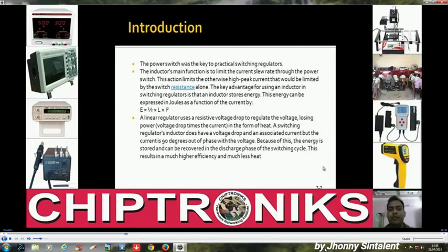So what are the basic differences between a linear regulator and a PWM regulator? In a linear regulator we generate a lesser voltage through a resistive element. We try to drop the voltage across a resistor, whereas in a PWM regulator we try to generate lesser voltages. I'm talking about the buck regulator. Buck regulators generate lesser voltages, because in a notebook motherboard we generally have buck regulators, as we are trying to get a lesser voltage from a high voltage.